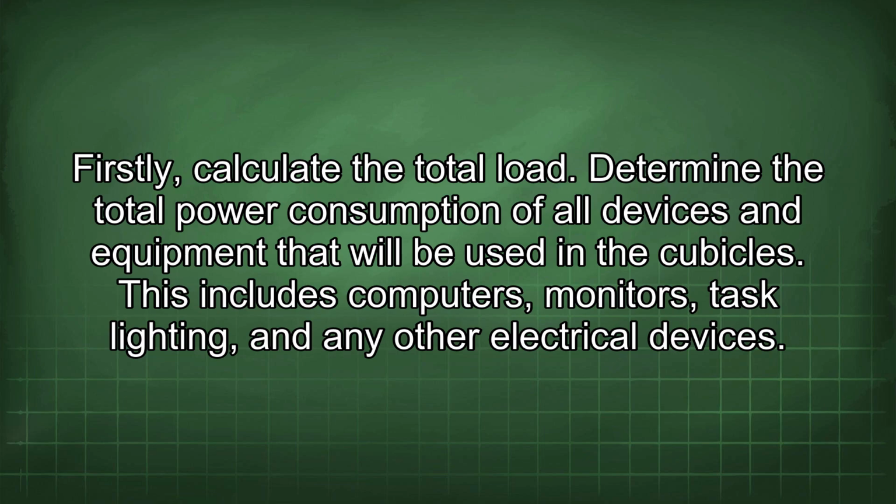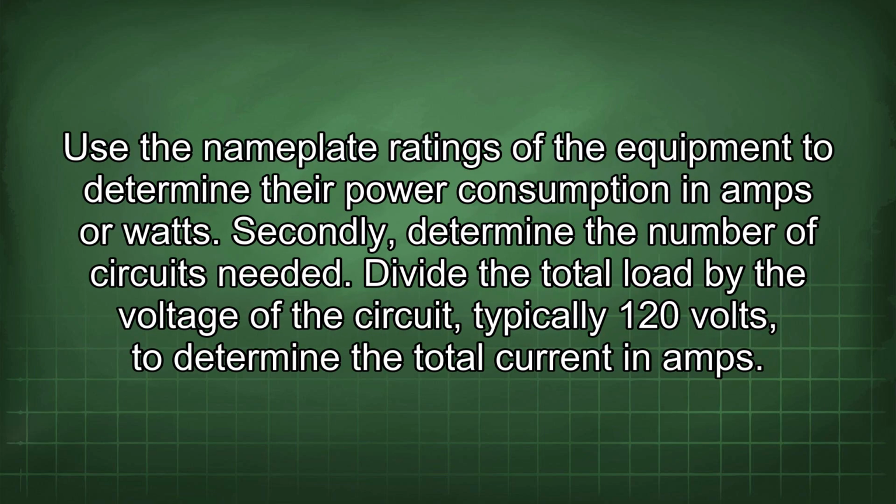Determine the total power consumption of all devices and equipment that will be used in the cubicles. This includes computers, monitors, task lighting, and any other electrical devices. Use the nameplate ratings of the equipment to determine their power consumption in amps or watts.